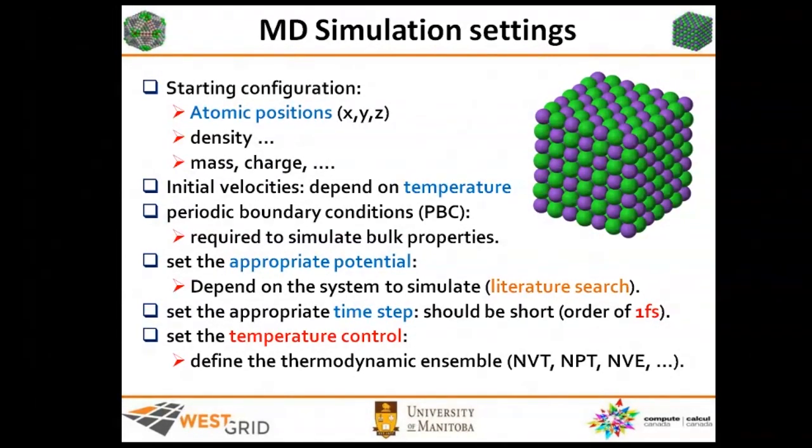There is another parameter to take into account, called the periodic boundary conditions. We are going to do the simulation in a very small system, for example, 4,000 particles, but the properties we compute are extrapolated to a large bulk system. So we use periodic boundary conditions, which means that you take your simulation box and make images of this box in different directions.